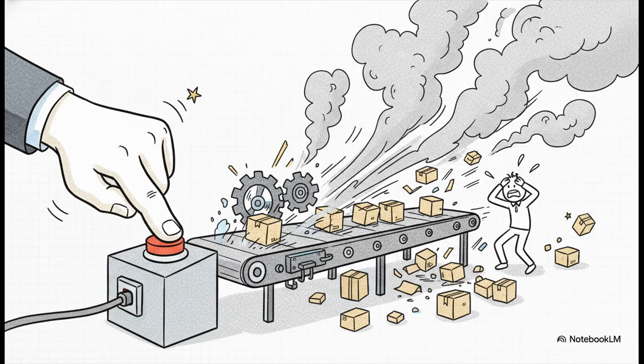Without the one-shot explicitly constraining the shift to a single step per event, that bit will instantly race through all the registers in a matter of milliseconds. Your entire assembly line process will trigger almost simultaneously, and it'll be a mess.